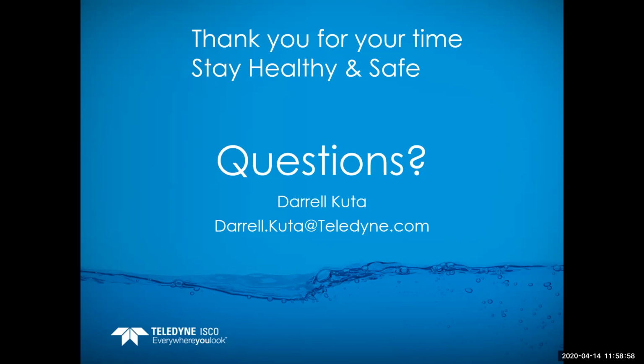Somebody's asking about how the temperature will affect a sensor, pressure transducer, if you had it in a dry pipe. So depending on the sensor, if you have it in a dry channel, say for a stormwater application, it's sitting at the ambient air temperature, and then when the colder rainwater goes over it, sometimes you can actually see a shift in the level readings.